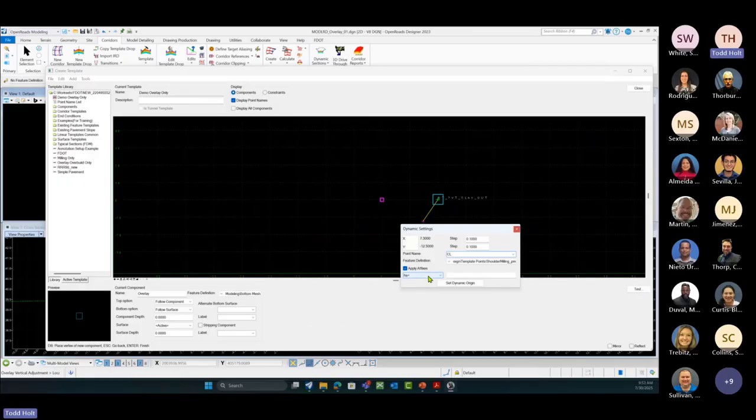And then our settings, or the precision inputs over here, we're going to switch this to our X and Y. So we're going to set that to X and Y, and that's going to equal our 0, 0. So that's going to put this point at 0, 0 within our grid. So I'm going to hit OK on there. All right, so there we have our center point.